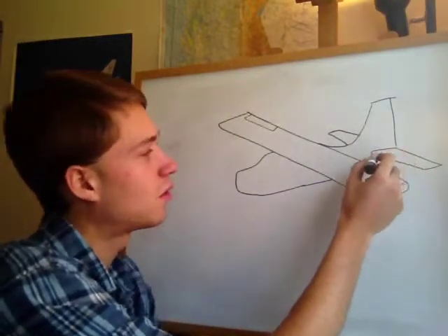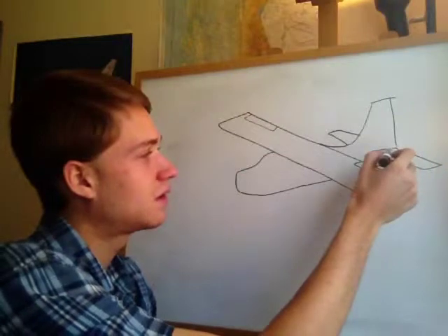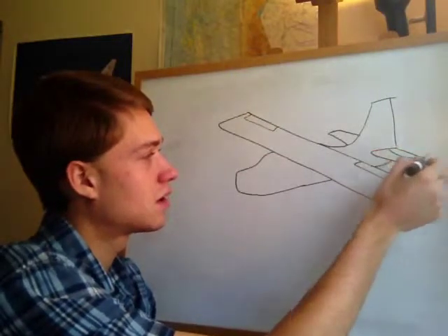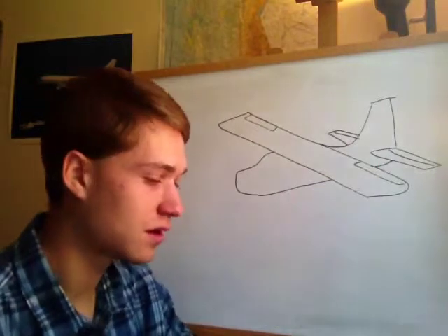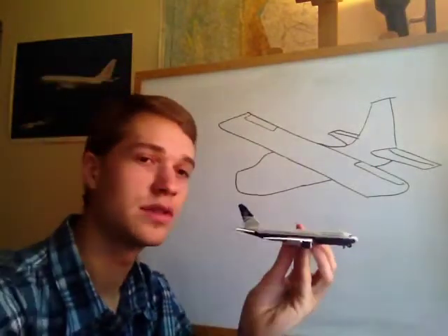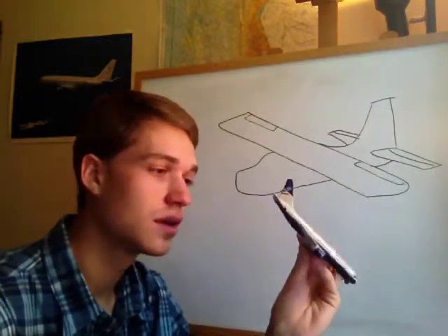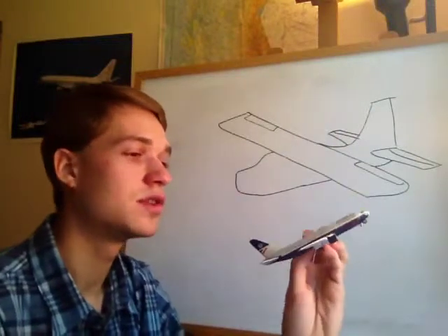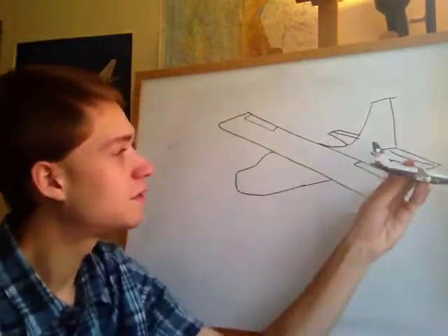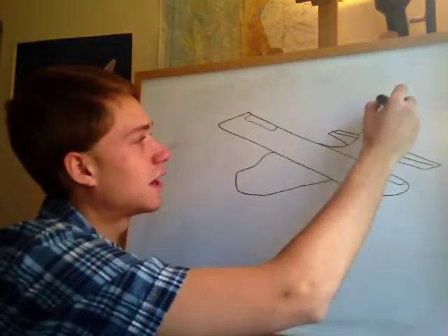We have the horizontal stabilizer in the back of the airplane. And what does that have? It also has a hinged surface on it, and we call that the elevator. And the elevator is used to basically elevate the pitch of the nose. It doesn't elevate the airplane like this, but you can raise the nose or lower the nose by deflecting the elevator control.